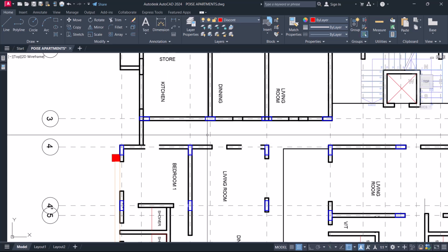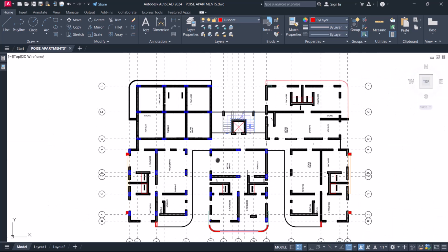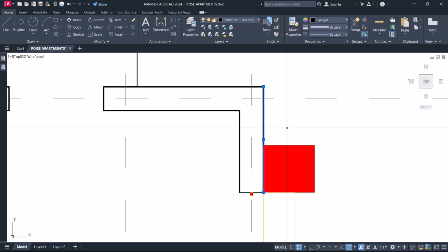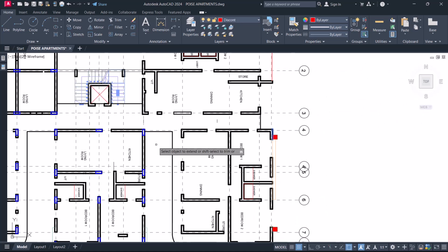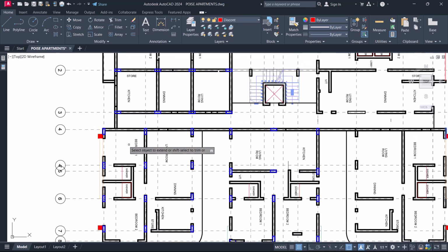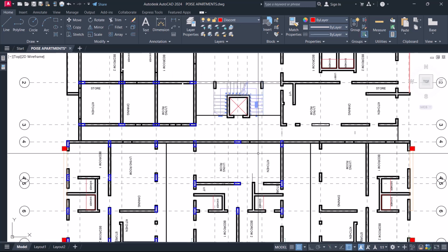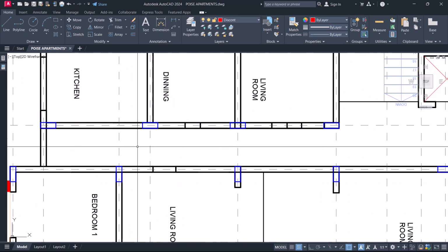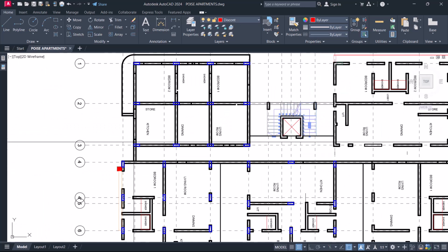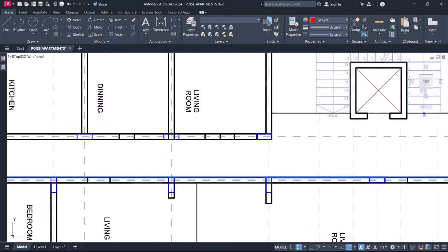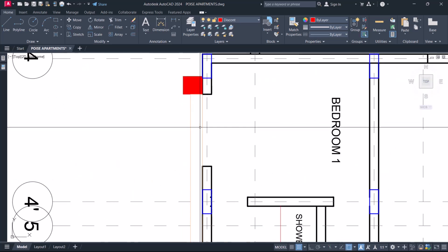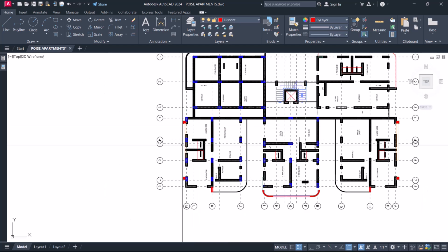Okay, so this is a straight line from here to here, so let's just extend using here as our boundary of extension. We'll extend from here up to this part. Okay, so this can be our slab area. It can be designed as a one-way slab. Okay, so this is okay. We can extend this to here, and the next is we have something. Let's see what this is speaking about.